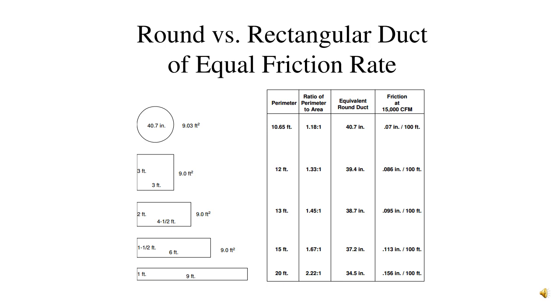The most important thing is we choose the right form of duct, which is rectangular or round duct. A second rule is the ratio of the width to the height of the cross section of the duct, if it is a rectangular duct, must be as close as possible to 1:1 and must never exceed 1:3. And the third rule, the width of the duct should be greater than the height of the duct. Just to recap again.